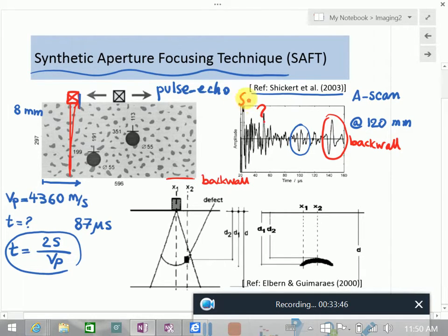So, all of that is just noise? Yeah. Because concrete is a very hard material to work with for nondestructive evaluation. If this was metal, you wouldn't see anything, and it would be beautiful. But this is a heterogeneous material. Every single particle is reflecting a part of the energy. And of course, if they are closer to the source, they are doing more. And I'll tell you in a moment that near the transducer, there are some really crazy things happening. So the transducer has a near field where things are very crazy. So that's why you also see a lot of noise here.